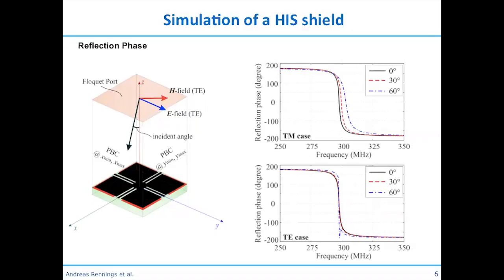The high impedance comes from a parallel circuit where you have here the conducting line that would be an inductor, and in parallel you have this capacitor here constructed from this MIM capacitor in series with another MIM capacitor. So at the resonance frequency, at the resonance between this inductor and this capacitor, we have the high impedance behavior.